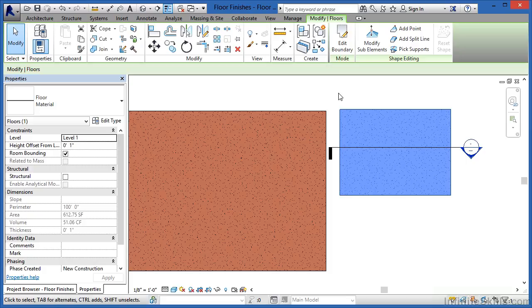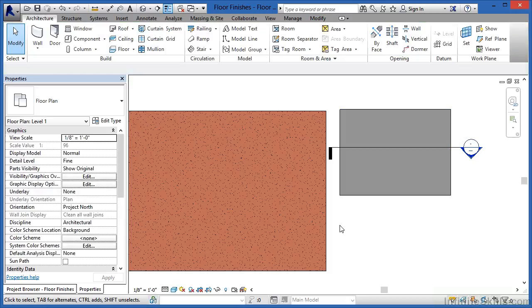And as we know, we make a lot of changes during the design process, so it's much more likely that we're going to need to make changes to that top finished material than it is not making changes to that finished material. So as a result of that, whenever you're doing finished floors, your best bet is usually to draw in the structural floor first, then add a finished material over the top of it, as opposed to the floor on the left, which has it all combined. And the reason behind that is it gives you more control over the material properties that are going to be associated with that floor, as well as where those materials are going to go to and how they clean up with the other structures that are related with that floor plan.